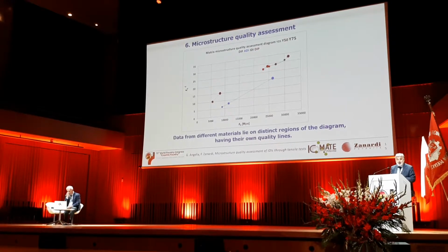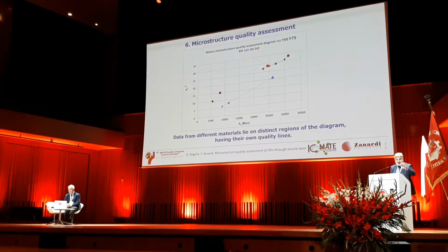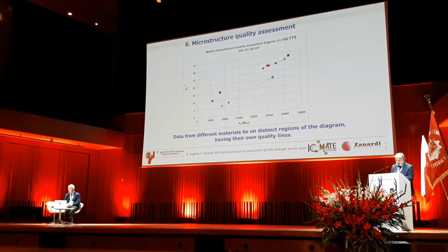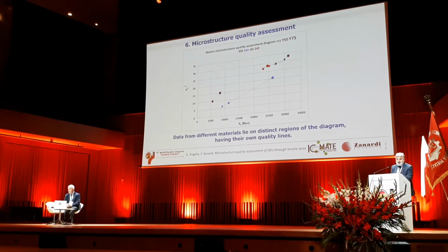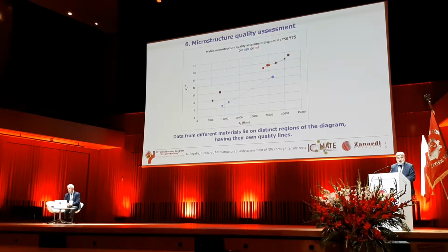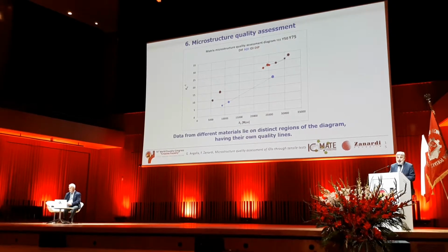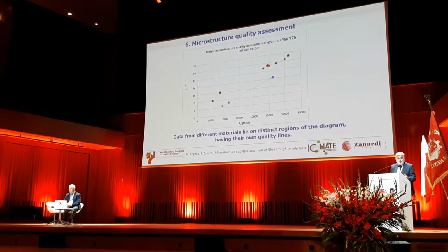In blue, you see the ADI materials that Stefano tested, and the big dot is 75, medium is 50, small is 25, and you see that in ADI there is a difference for the 75 thick sample because of the addition of alloy elements we are obliged to use for this kind of thickness.